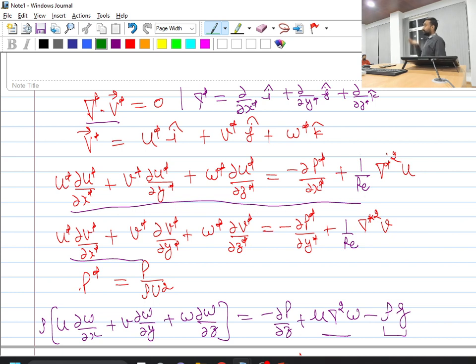That is something which we do the majority of the times for compressible flow analysis, where we have, say, an aircraft moving in the atmosphere. Their velocity of the flow will be so high that our Reynolds number is extremely large, viscous effects are negligible, and we can actually neglect these viscous terms.